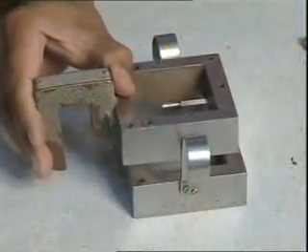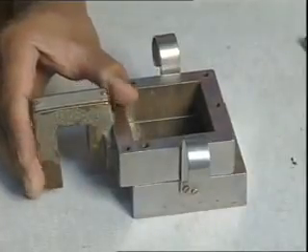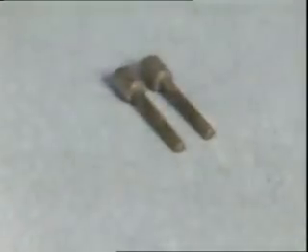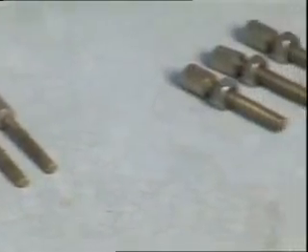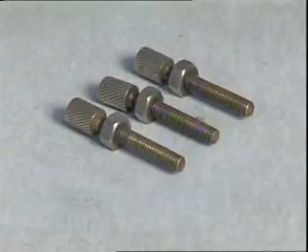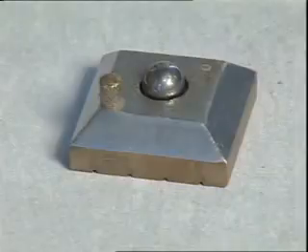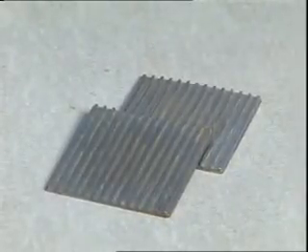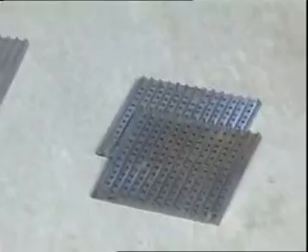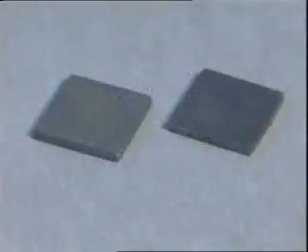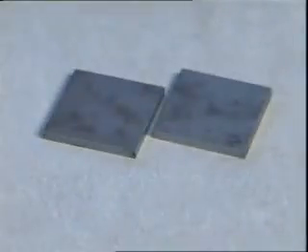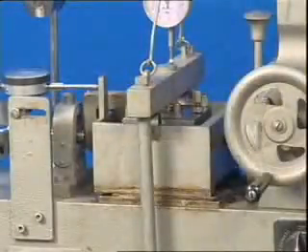It is horizontally divided into two parts, having connecting pins, spacing screws, base plate with cross grooves on its top face, loading pad with a steel ball on its top, two pairs of grid plates, one plain and other perforated, porous stones, one pair, metal plates, one pair, container for shear box.